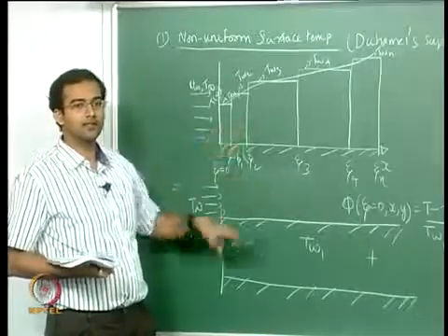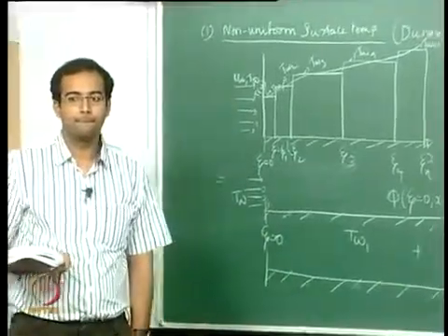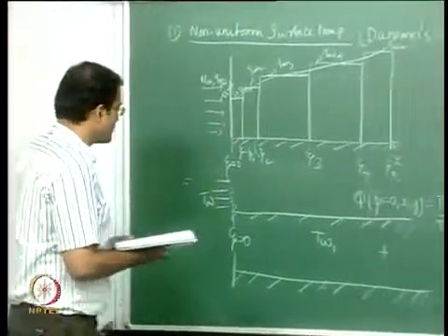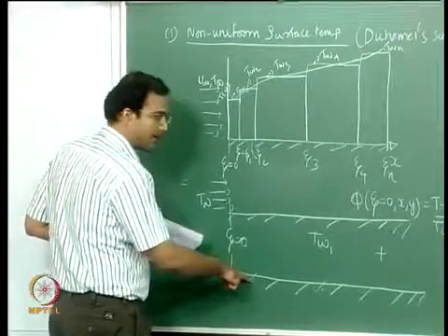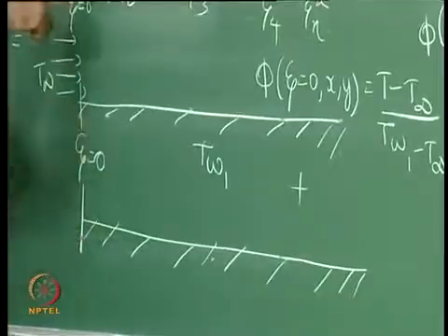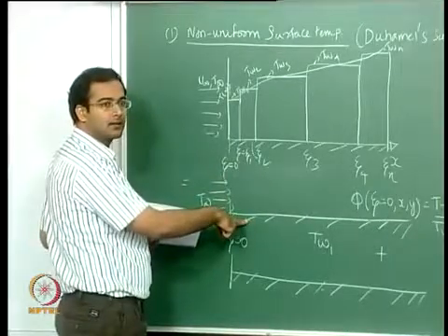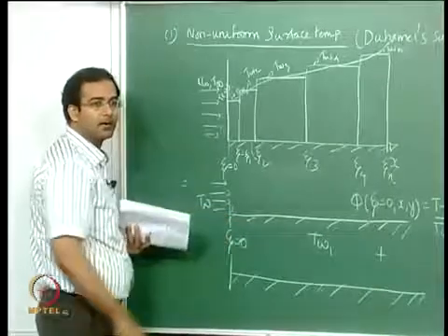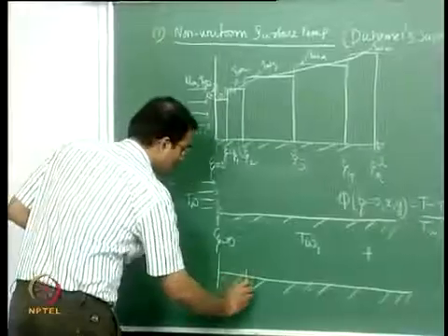So what is the next problem that I have to solve? To do that, what should I do? I should not solve for any heat transfer problem till zeta 1, because I have already solved it here. So I should maintain an unheated starting length till zeta 1.